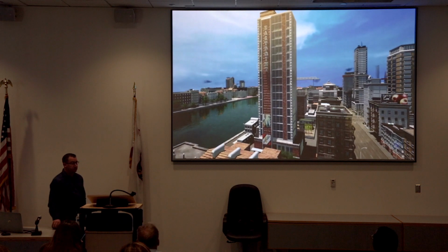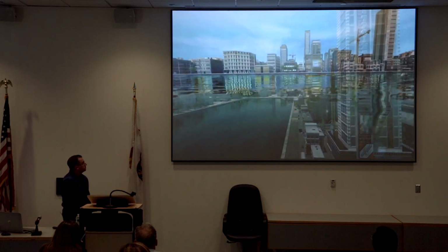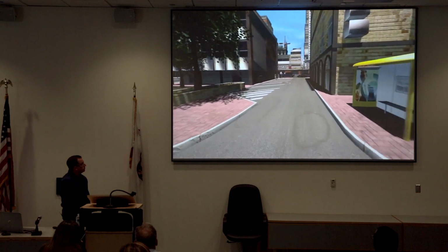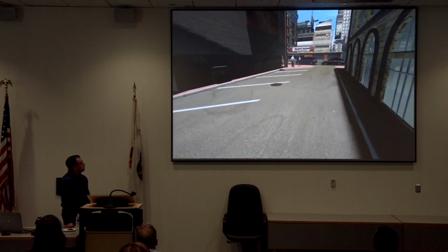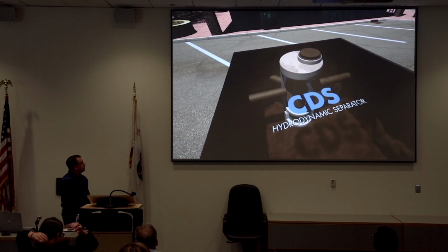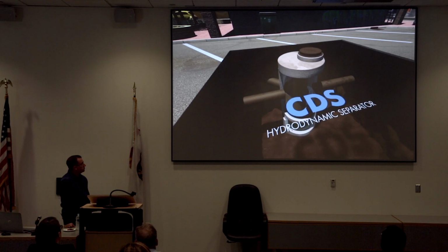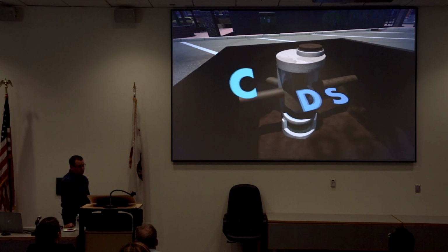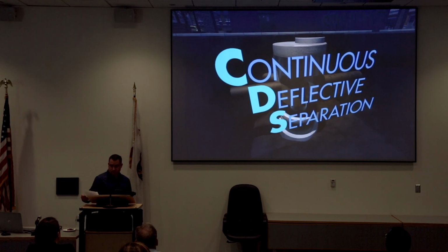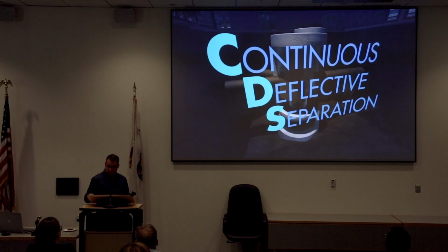Stormwater regulations often require treatment of runoff before discharge. This can be a challenge on sites where there is limited space for an above-ground solution. The Contech Engineered Solutions CDS Hydrodynamic Separator is a below-ground flow-through treatment device that uses multiple treatment processes, including swirl concentration and continuous deflective separation, to screen, separate, and trap trash, debris, sediment, and hydrocarbons from stormwater runoff.